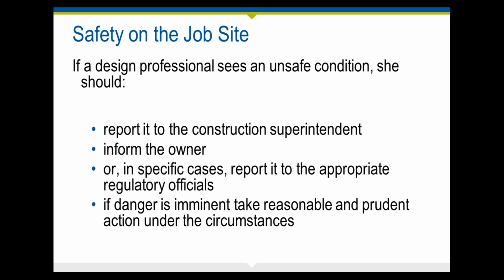And this is always a topic that generates a lot of questions from design professionals when we talk about construction contract administration responsibilities. So let's now talk about the issue of submittals. And submittals really fall into various categories, but you should think of submittals, which we'll talk about, in the same line as RFIs, a request for information. A request for information is really the opportunity for the contractor to ask for information, to ask questions about the drawings, about the spec sections, whatever it is that they need clarification on. And then they're really risk management tools. It lets you know what the contractor is seeing and what they're thinking.